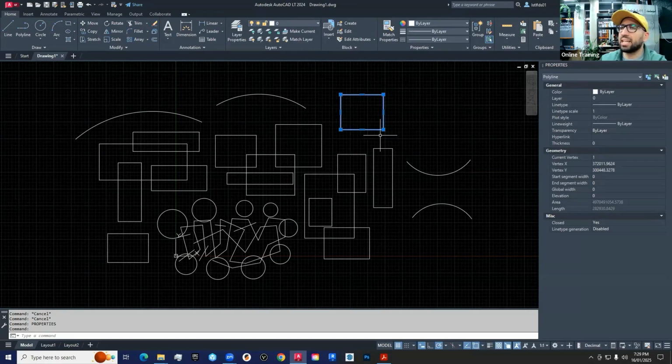So if you select a rectangle in AutoCAD once created, it's called polyline. It's a bunch of connected lines. Poly means more than one, so there are more than one line connected together. And right there, you can check the area and check the length of this one. So if you want to know the area and the length of your objects, you're going to find them right there in millimeters. That's why we have a lot of digits right there, depending on the scale you're currently using.